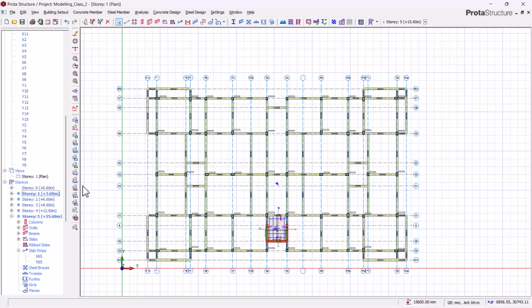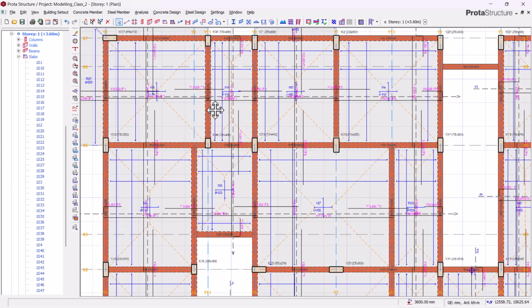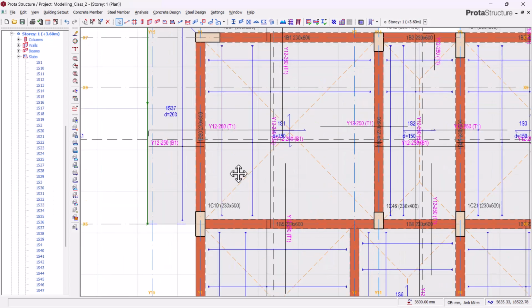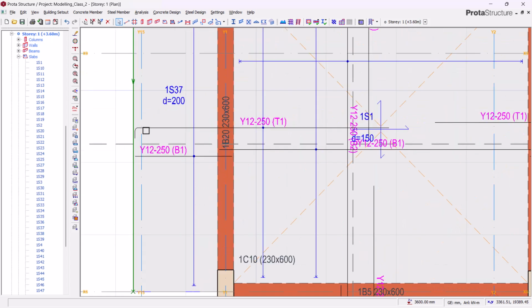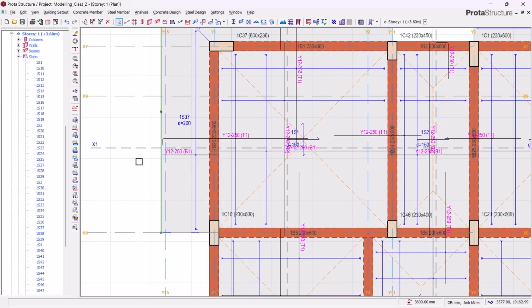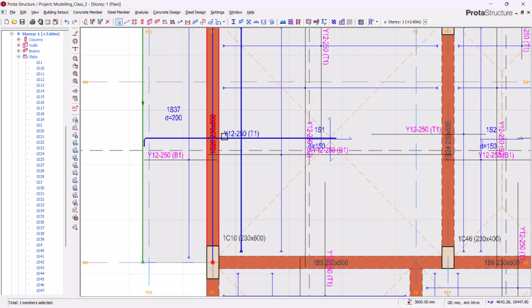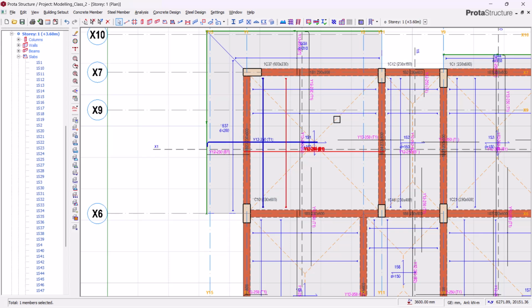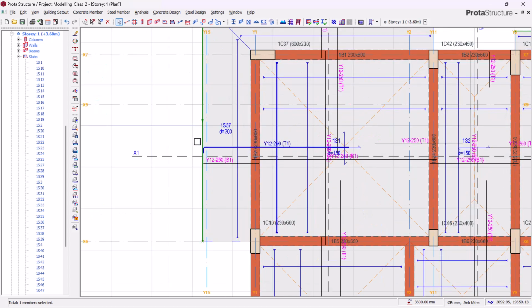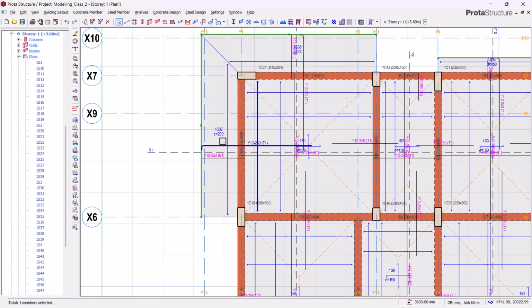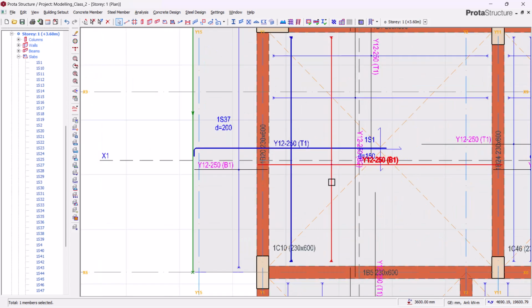So we'll come back to story one, and as you can see, we have our top slab because of this cantilever. Remember, if you are designing to BS code, it requires you to return this reinforcement back into this span at L over 4, which is the length of this supporting span, all over 4. Okay, so if you check, this is in alignment, that's for the top bar.